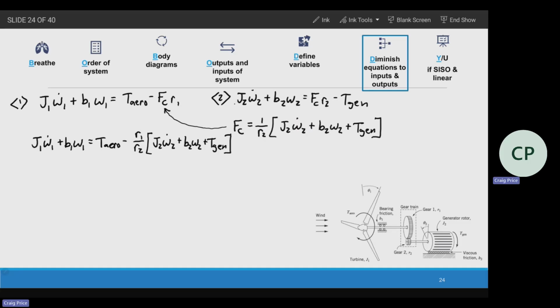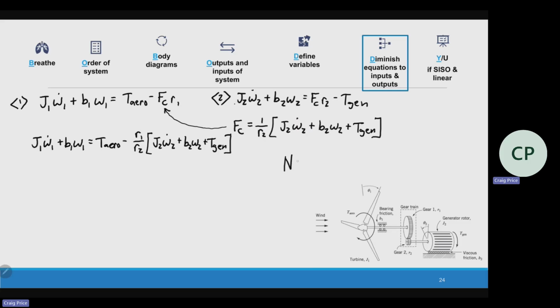Yes, they are. We have the gear ratio N, capital N, that's equal to R2 over R1. So driven gear over driver. It's also related to the number of teeth. Now that also gives us a relationship between the torques. So the larger radius you have, the more torque you have. This is inversely related to the speeds.